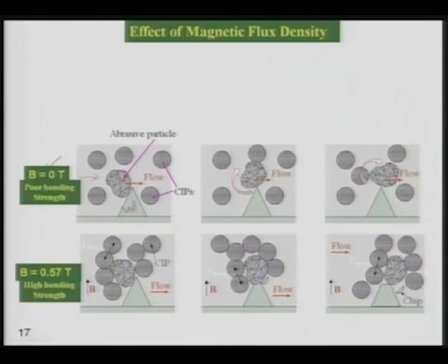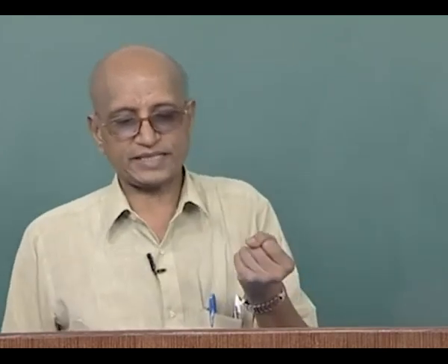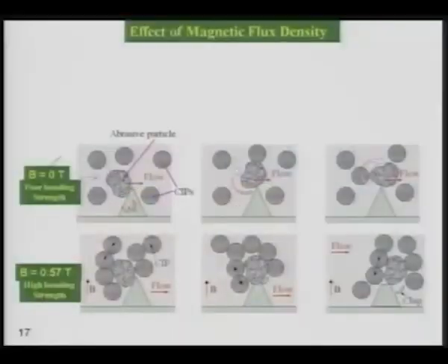This is the workpiece surface, and without removing any material, because there is no strength in the iron particle, or there is nothing which holds the abrasive particles and applies the force. So it just jumps and flows over the peak and comes out without any removal of material.